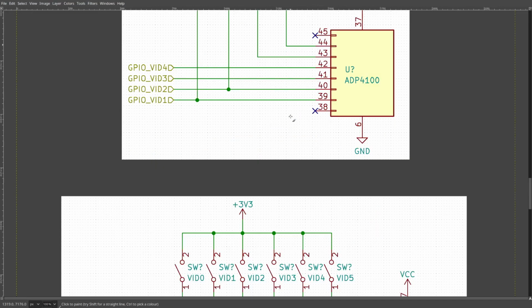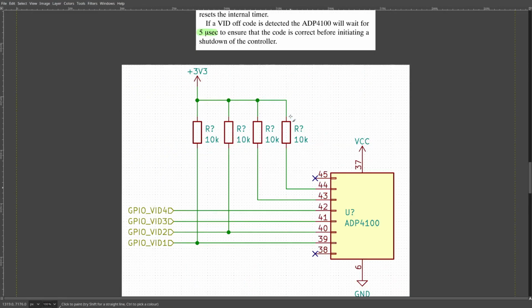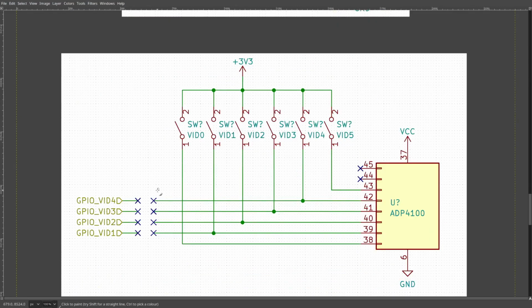So then when we want to look at vid modding a controller like this, what we want to do is disconnect the GPIO pins from being able to influence the vid so that we control it. Now, if, for instance, this was still connected because for some reason there was just a via that you couldn't really cut the trace between, it would just cause too many issues.